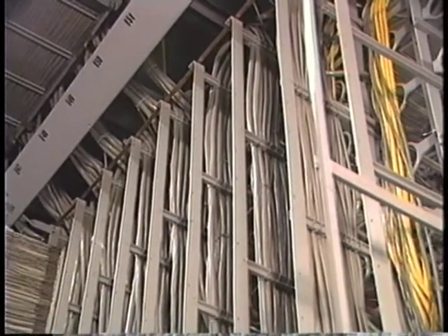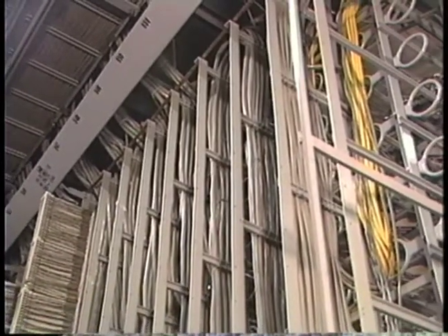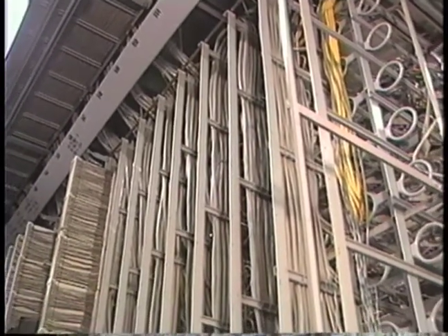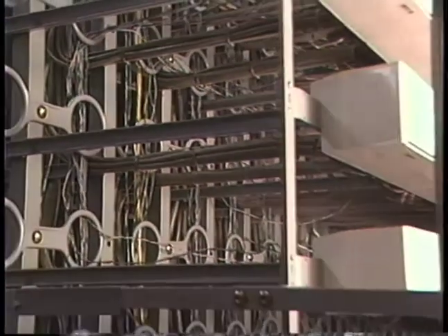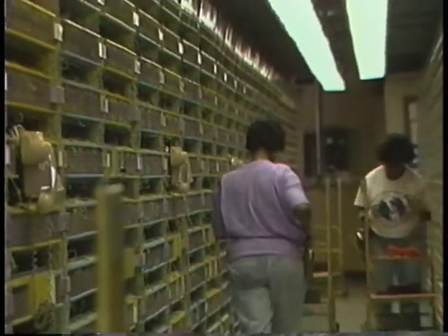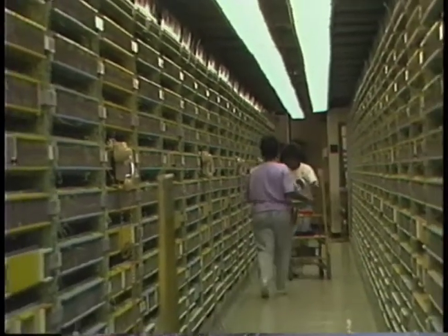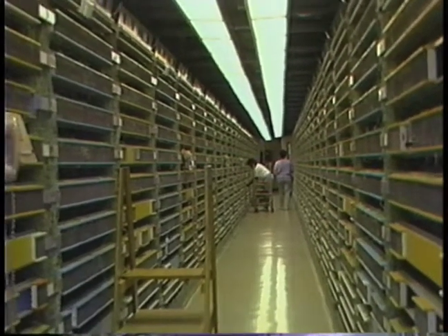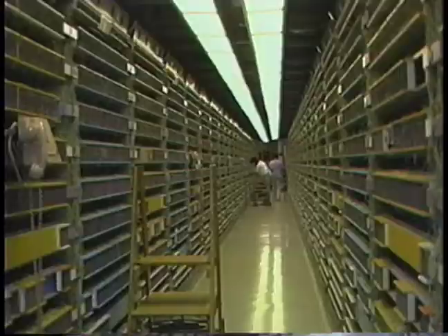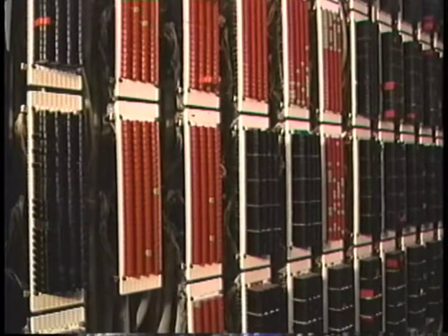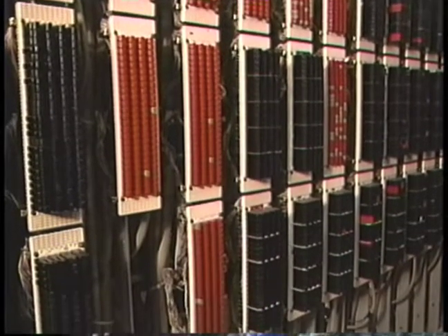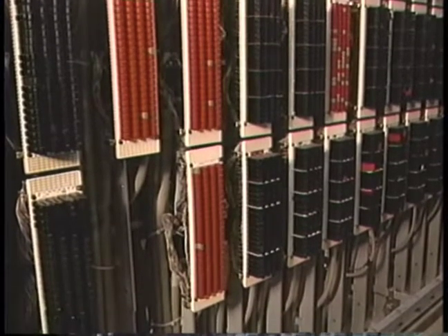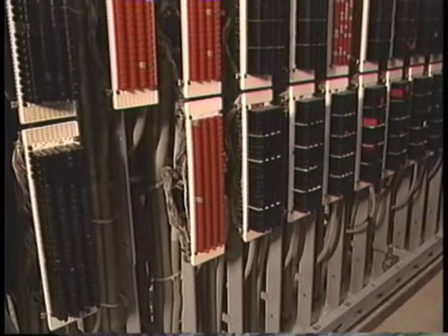All of this transmission equipment is connected to the switching equipment via a distributing frame. A distributing frame terminates wires in an orderly, structured fashion so other wires can be attached. There is a main distributing frame connecting outside lines coming from subscribers to the central office equipment. This MDF has lightning protector devices called heat coils. If lightning strikes outside lines, the switching equipment won't be damaged.